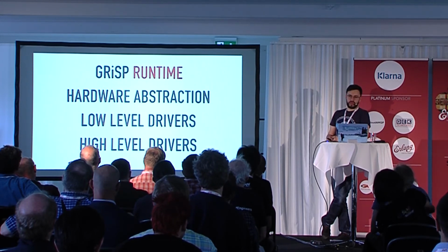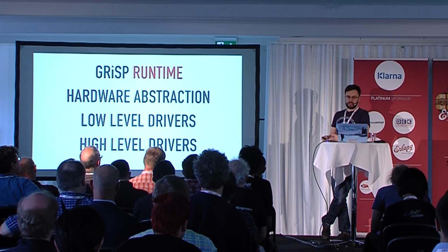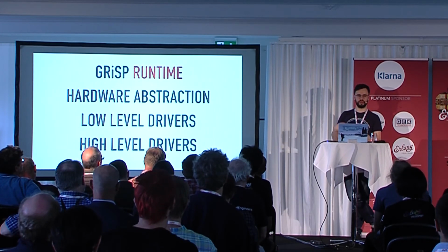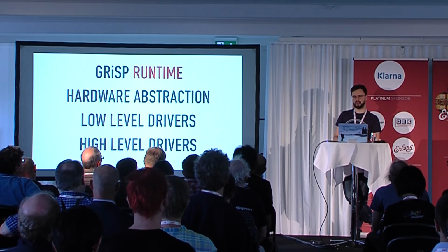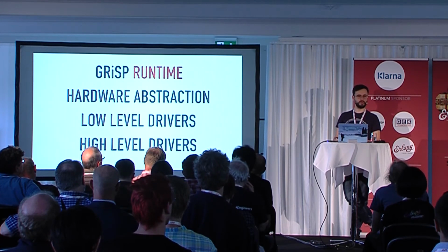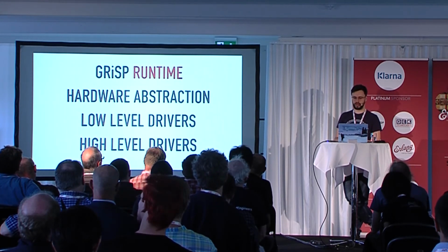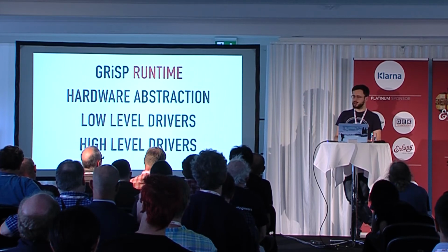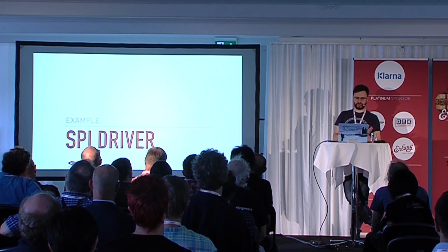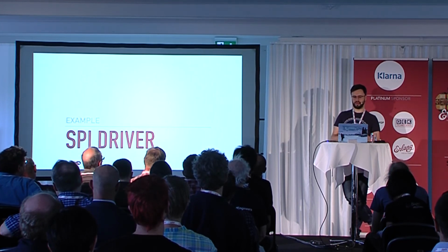And then we have high-level drivers for using the LEDs, which I showed you, for reading the dip switches, and for interfacing with PMODs. So we're trying to write more and more PMOD drivers. So the hope is that for at least the most common useful PMODs, we already have ready-made Erlang drivers that you can build Erlang applications with. I'll show you an example of how the SPI driver kind of works from C to Erlang, so you get a feeling for kind of what's involved here.